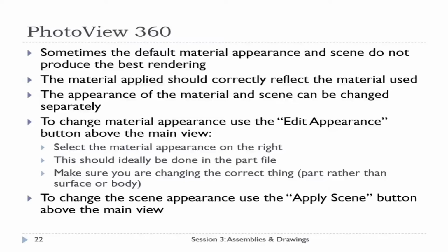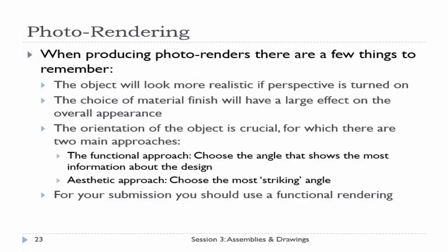So to change the material appearance, we use the Edit Appearance button. Using Edit Appearance, you can apply different colors or different finish types to the components or faces. And similarly, we can change the scene using the Apply Scene button in the main view menu.